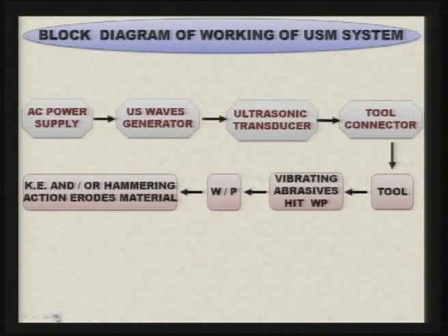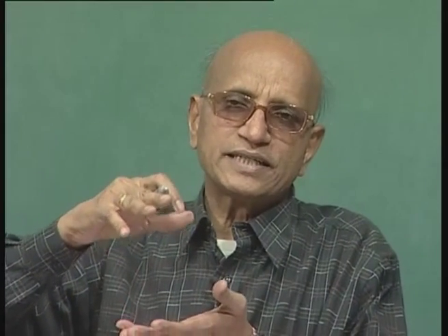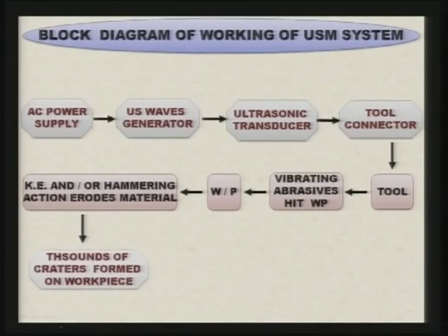Because of their high velocity and large number, they hit the workpiece, and their kinetic energy, or hammering action, erodes the material from the workpiece. Thousands of very fine craters are formed on the workpiece, and this results in a finished component.